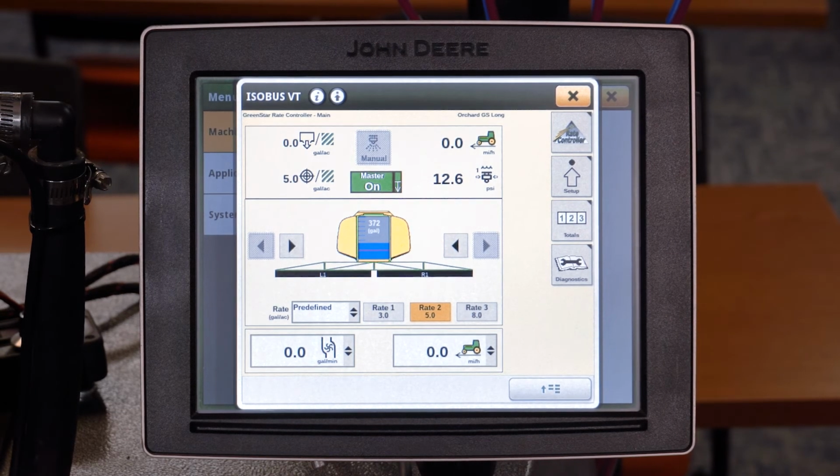Sometimes a tight strainer can gel over, especially when a cold product is going through it. When you turn around, some of the gel will dissolve and the system will begin pumping okay. But as the gel returns, the rate will drop off. A larger mesh strainer can help. Then check, are there any other inlet restrictions?